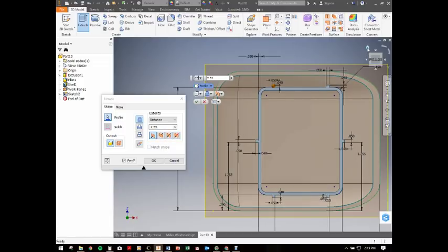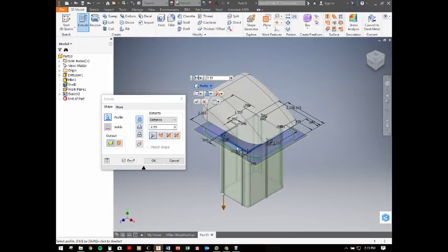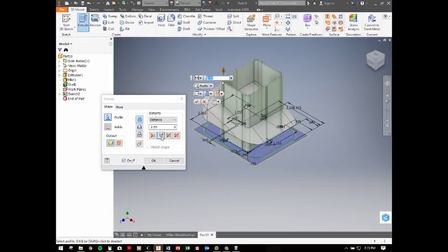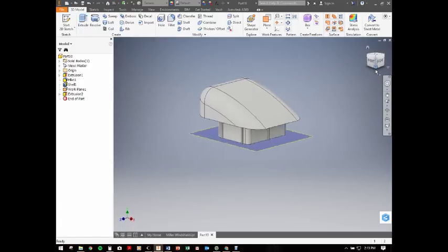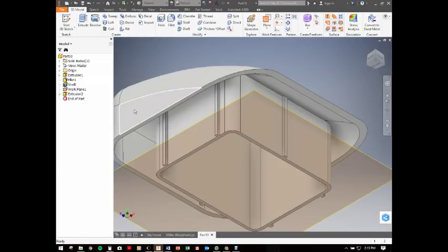If I go over here and show you this, right now it's going down from this plane. If I was to just go in, you see how it pokes through the roof in here. So I don't want to go by a set distance because no matter what I do, it's either going to be too short on this side or too long on the other. That was the whole point of using this work plane in the first place, is that instead of distance, we're going to go to the next feature. That's what to next means, is the next feature. So now I hit OK, and this created this projection all the way up, and so it's mated now with this surface up on it without sticking through it.